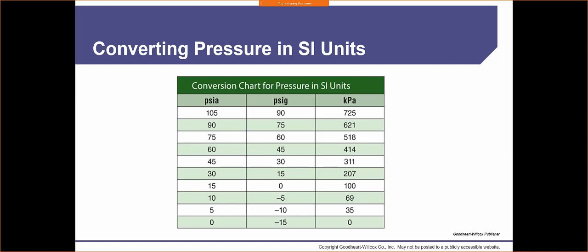So what ends up happening is we've got that 14.7 psi being exerted on us continuously. That's going to affect our gauges. Okay. So what we do is we sort of zero out our gauges. It's sort of like a scale. All right. If I wanted to, let's just say, figure out how much does water weigh? Okay. I'm going to put a container on the scale, and I'm going to pour water into that container. But my measurement on my scale is going to be off because I didn't zero out the scale. I haven't taken into account the weight of the container.